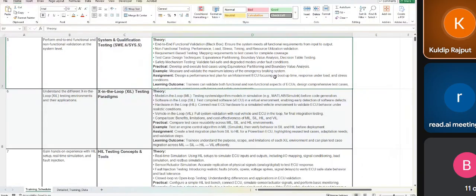In the SIL environment it is quite easy, the software will look fine, but these kinds of issues are captured easily on the HIL system. There is a concept called active high and active low switch. If the left turn indicator input switch is mapped as an active low switch, and you provide the command as turn on, like we are sending logic 1 to turn it on and logic 0 to turn it off, that is actually the reverse of the active low principle. These are the kinds of use cases we'll be discussing as part of the debugging sessions.